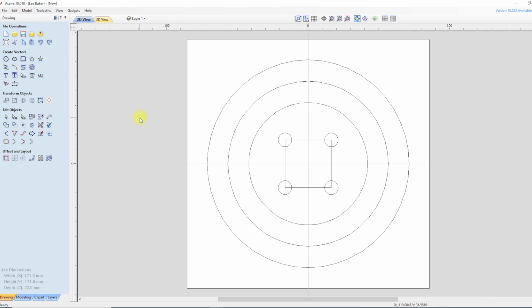If you want to add text with a serif, I think it's called, then if your material isn't quite flat, sometimes this can show in the serifs not machining evenly. This can be overcome by skimming the surface of the button first, depending on how far out of flat it is. But to keep this project as simple as possible, I'm just going to use the Arial font.